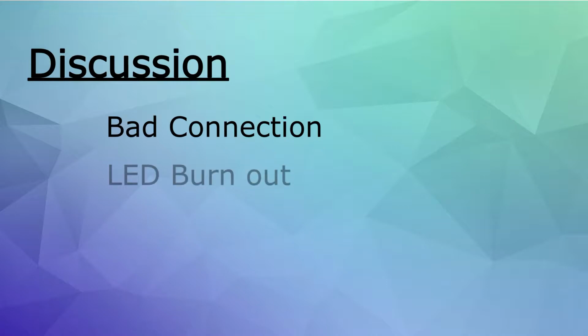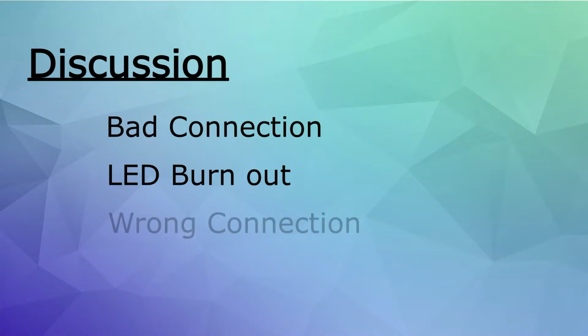Second is the LED burning out. Our LED burned out because of excessive current flow from the power source, which is 9 volt. In order to overcome the problem, we reduced the power supply to 5 volt. Then finally, the problem that we faced is wrong connection. We failed to identify the positive and negative terminals of the components, which caused the circuit to be incomplete and not function.